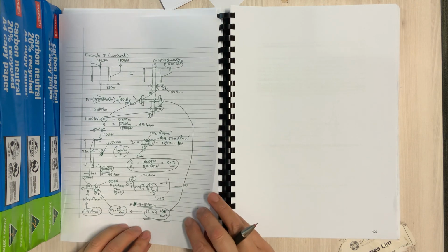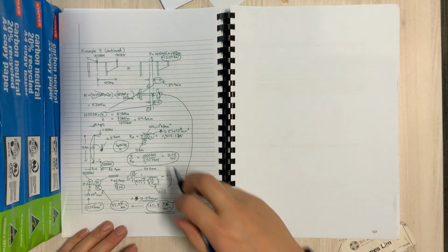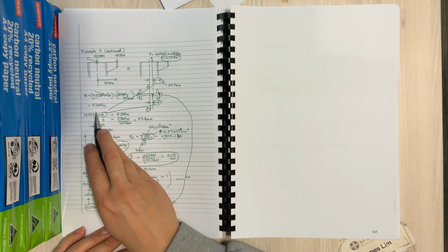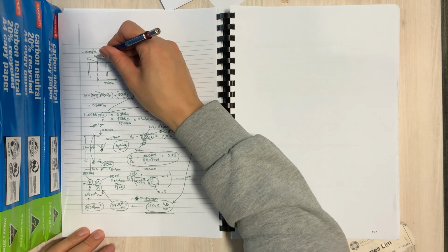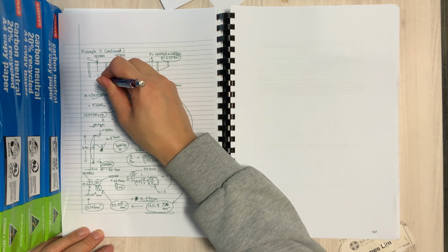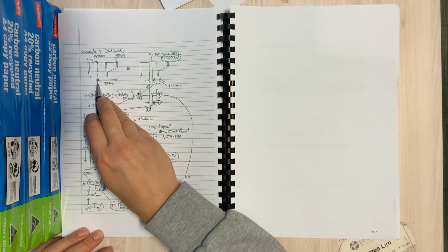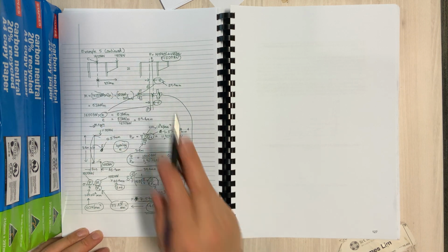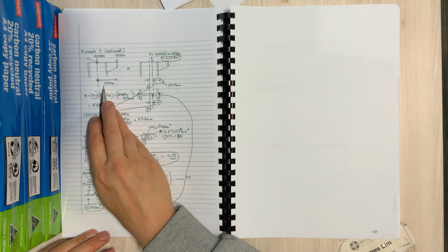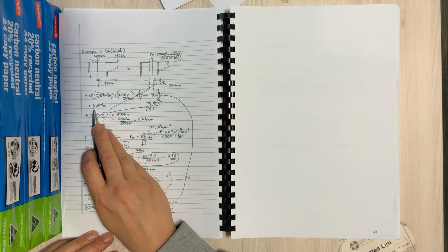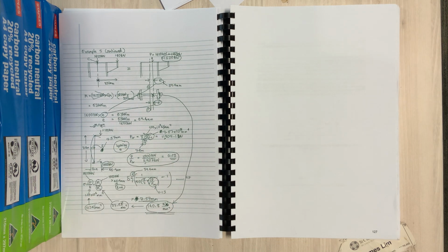So let's go through the calculation. Again, drawing out the bracket, and then down here working out the bending moment. You want the bending moment from here along the centroid. So the bending moment caused by the 180 would need to be multiplied by the 350 millimeters, which is going to turn out to be 63 kilonewton meters.